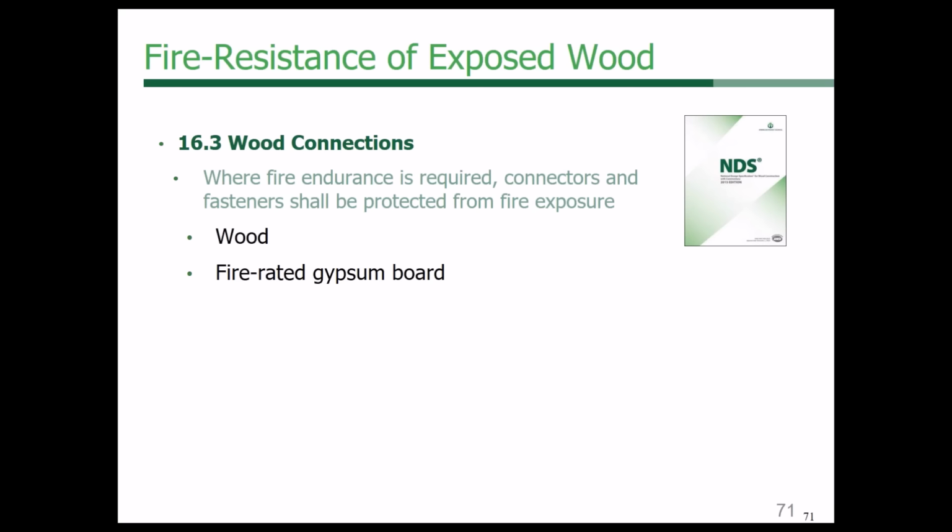So for example, if you calculated it for 1 hour fire resistance, the connection of that member to whatever is supporting it needs to be provided with the same amount of fire resistance. And to provide that fire resistance, one could use wood or gypsum.